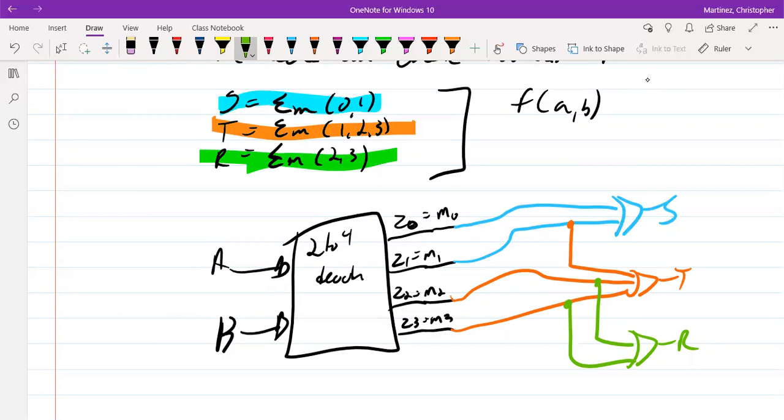If we wanted to build this on a breadboard, likely this is just 2 IC chips. One IC chip for the decoder. And then usually on an IC chip for OR gates and AND gates, you usually have 4 gates themselves. So you can easily see that we can build this with just about 2 chips. All right, so this gives you an idea of a bigger black box as we start to do modular design.